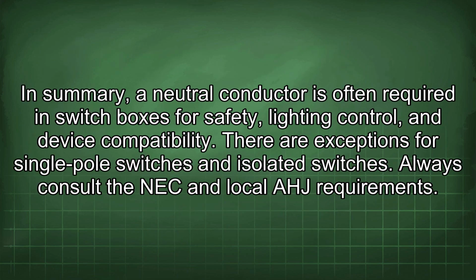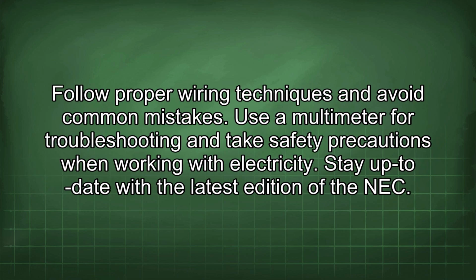In summary, a neutral conductor is often required in switch boxes for safety, lighting control, and device compatibility. There are exceptions for single-pole switches and isolated switches. Always consult the NEC and local AHJ requirements. Follow proper wiring techniques and avoid common mistakes. Use a multimeter for troubleshooting and take safety precautions when working with electricity. Stay up to date with the latest edition of the NEC.